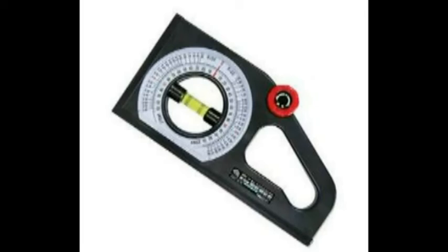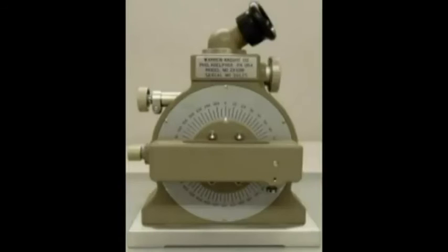Okay, and the next clinometer is the optical clinometer. It consists of a rotatable turret which is mounted on the base. The spirit level is provided on the turret, and the readings are taken by a measuring microscope on a graduated scale provided on a fixed circular glass disc concentric with the turret. With this instrument, an angle even equal to 1 minute can be measured. The vernier scale is provided in this microscope.